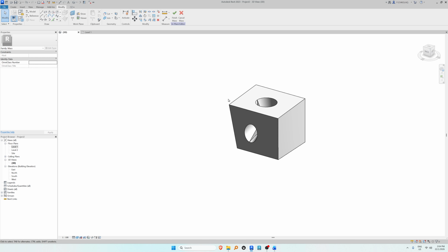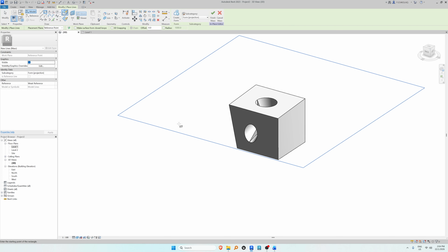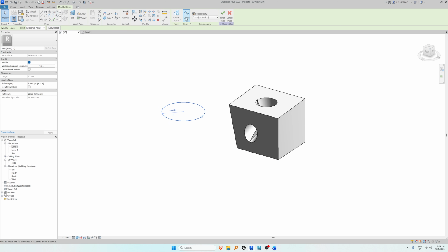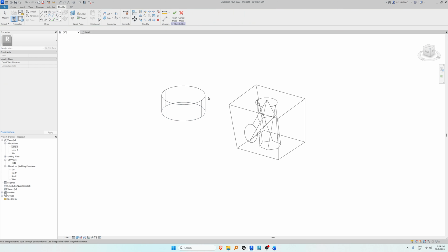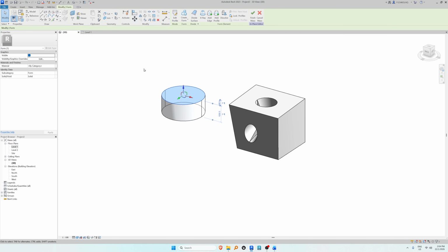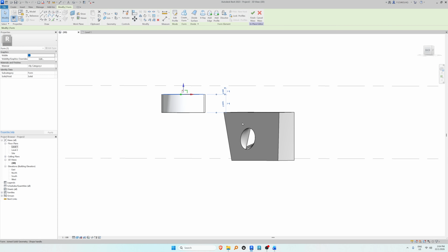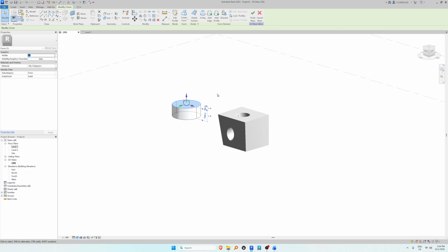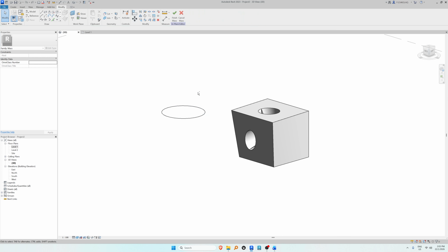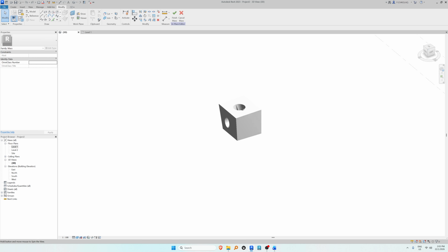We can keep working in this environment and keep creating more shapes. Okay, let me make a new shape. Select this, create form, solid form. It will keep creating these shapes. You can keep doing that. But we want to make a new object. So I'm just going to undo this part only. Control Z, Control Z. We go out of the thing.